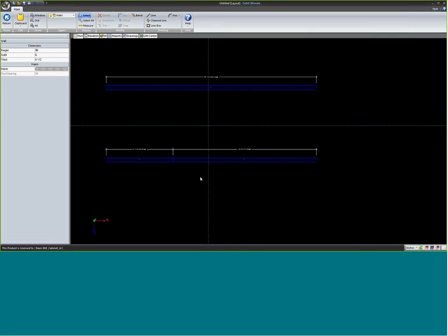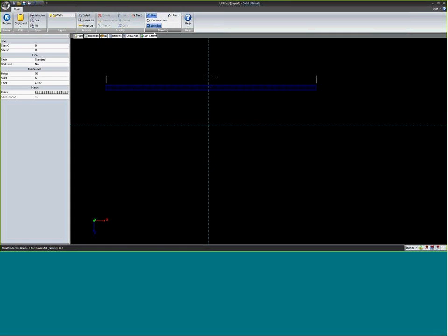That's okay to do, other than the fact that when I go to elevation view, if I have cabinets along this whole run, I'll only see the cabinets that are attached to this wall when I look at that wall's elevation. So you typically don't want to do that. But when you go to a T-wall that you want to float somewhere in the middle here, if I try to click on this wall, it looks like it hasn't done anything. But if you look over in the upper left corner, under clearance, it's trying to attach to this wall.